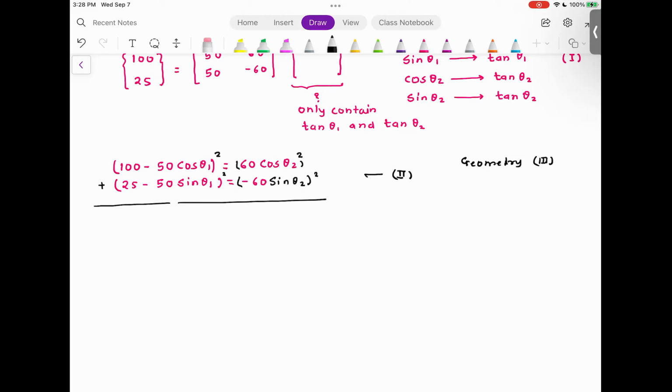How do we eat an elephant? In pieces. So what it means is if you have this 6 degree of freedom robot, separate this out into first 3 degrees of freedom and then next 3 degrees of freedom. The assumption is joint theta 1, theta 2, and theta 3 are responsible for px, py, pz.